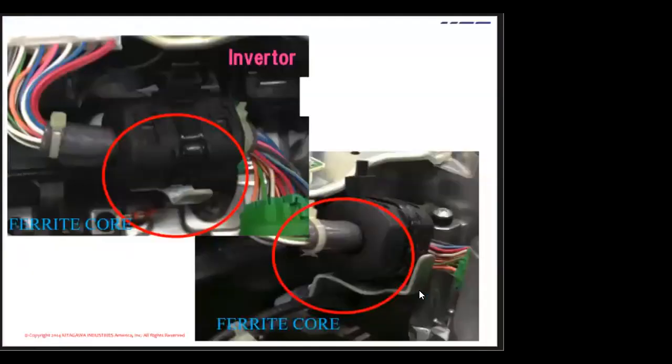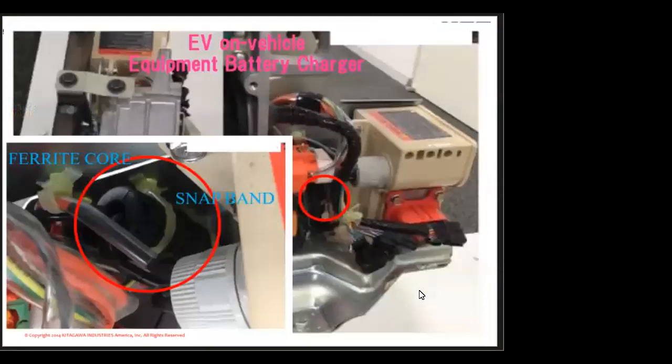Here you can see a cable tie was used to hold the ferrites in place. The casing of this ferrite was custom made to hold on to the cable ties. And this cable tie is a type of snap mount, which is mounted onto the metal clip below. And for this one, by inserting the ferrite core on the cable of the voltage monitor sensor, you can dramatically improve the immunity of the voltage monitor unit. And a special ferrite core for high frequency type should be used for effective results in this case.